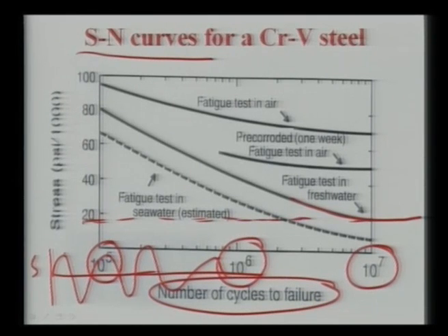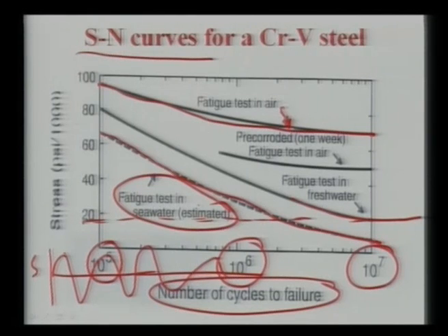What is important to note from this slide is that when you do this fatigue test in air, this SN curve is at a much higher level compared to when you do the same fatigue test on the same material in seawater. Seawater is largely a NaCl containing solution, and the sodium chloride solution here essentially mimics the typical in vivo environment or body environment.